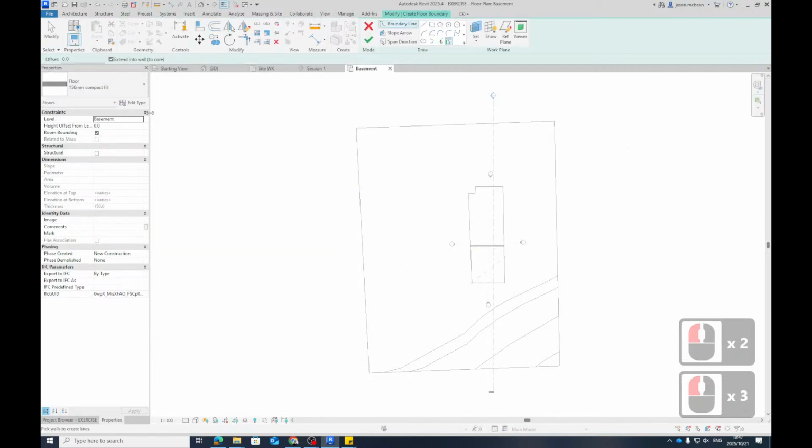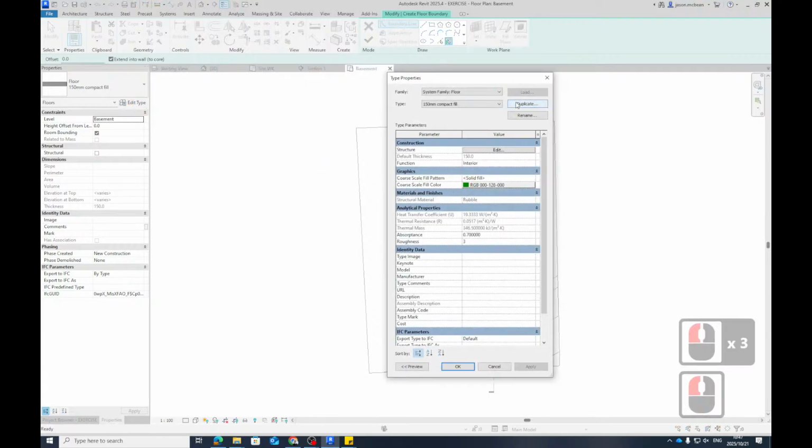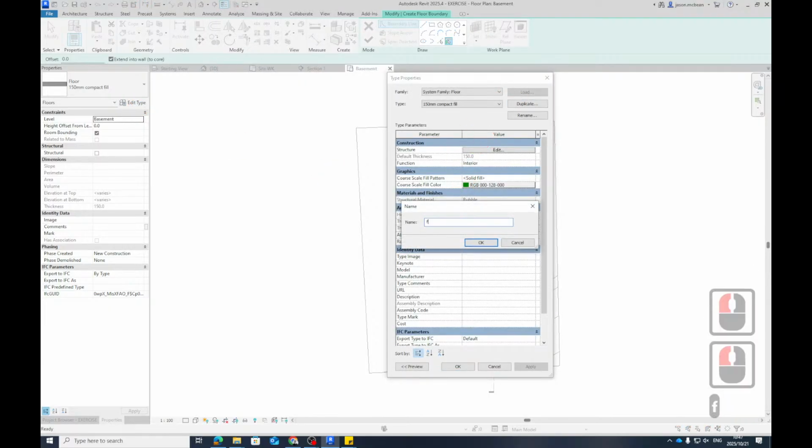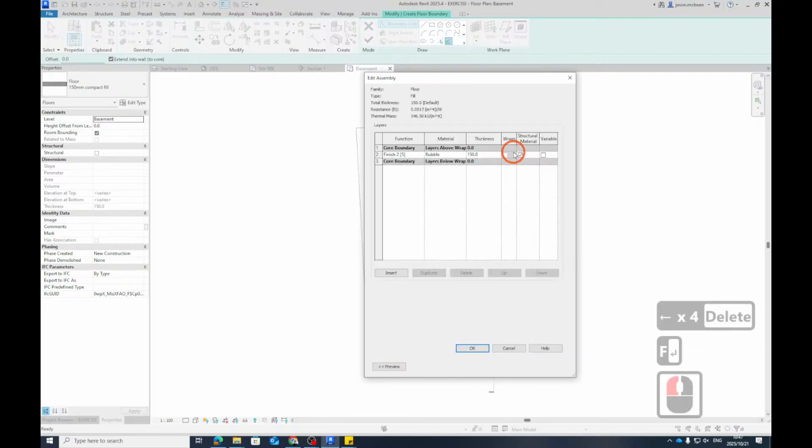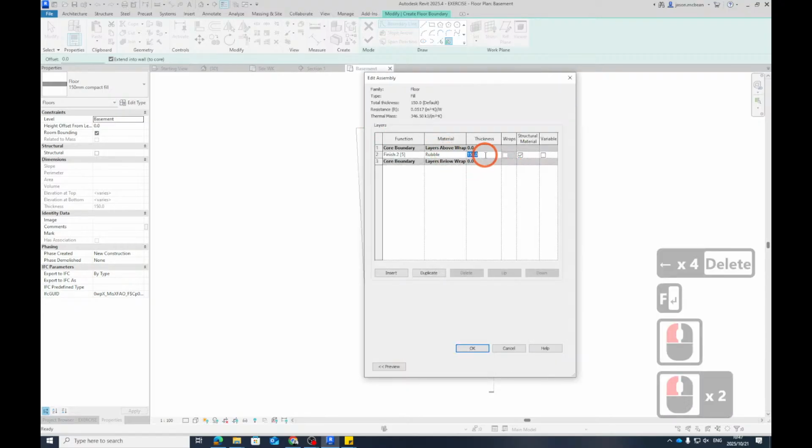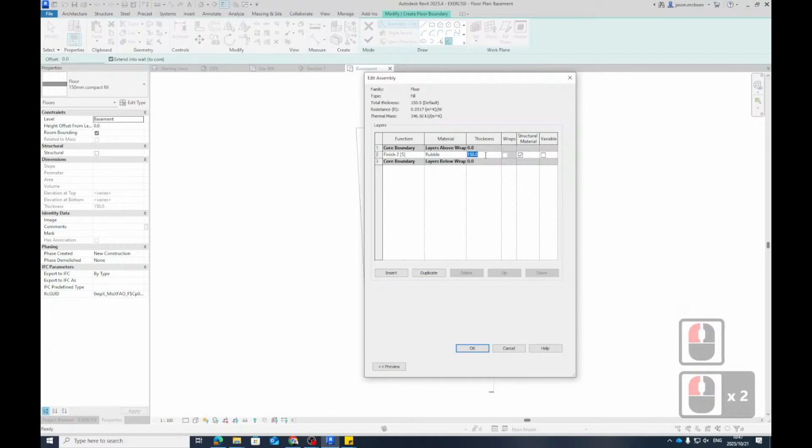In basement, I'm going to go to edit type, I'm going to duplicate. I'm going to call this fill. Now, I'm going to edit its thickness, and the fill, these are usually in layers of 150 or 125. They get packed in layers, they get compacted, then they pack another layer, compact it. Okay, so they're done in a certain way, but we only show the first 150, we don't show the rest, typically.